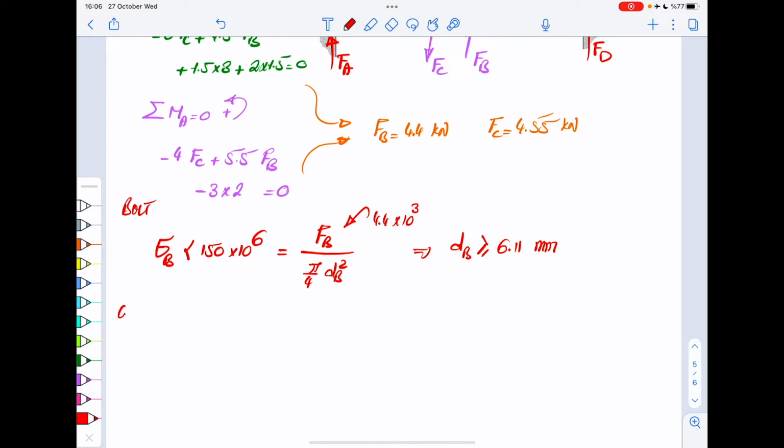So now the next thing you want to do, so this was, let's say, the bolt itself. Now you want to also analyze what happened to the washer. Now, washer is like a hollow cylinder, right? So the area of that would be pi over 4 times, let's say, outer diameter, which is what we want to compute. This is the washer diameter minus the inner diameter of the washer. And now the inner diameter of a washer is basically the diameter of the bolt, right?